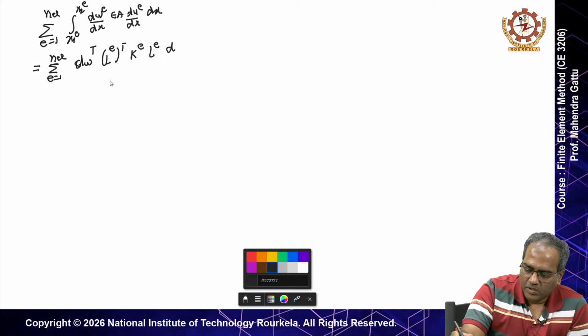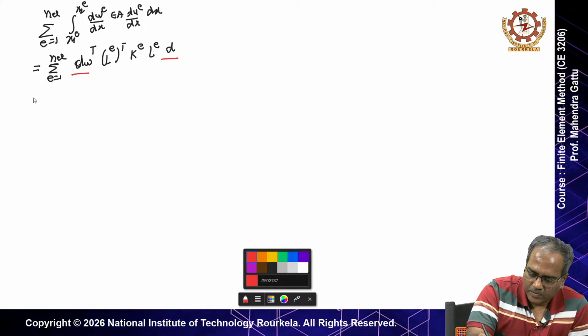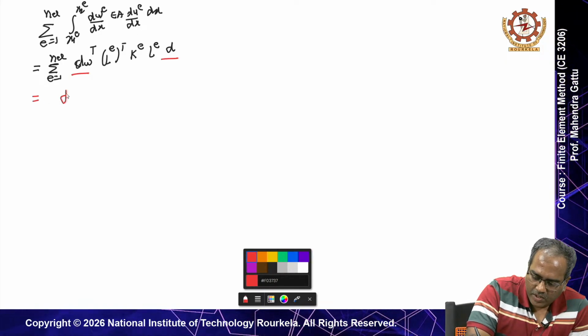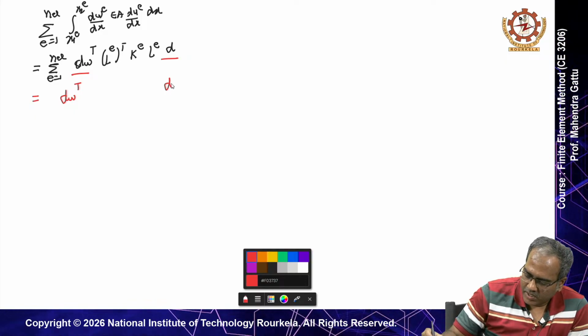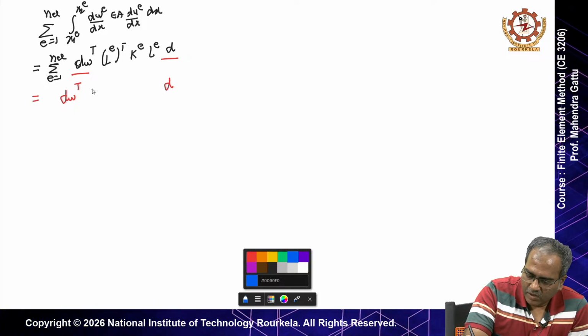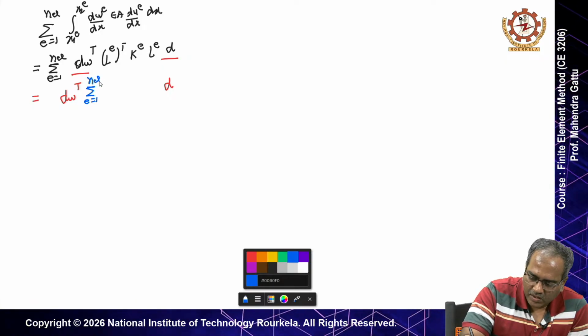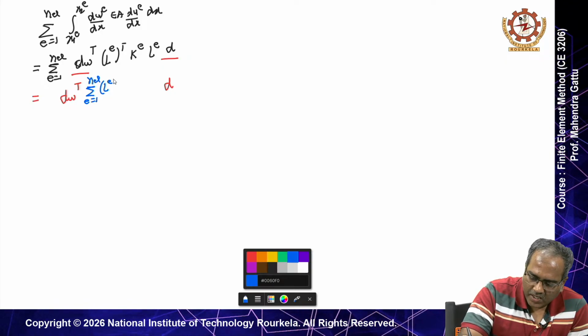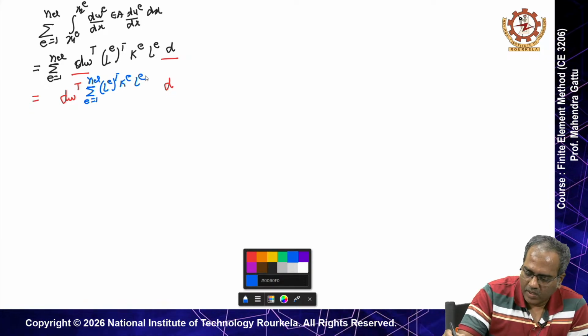Okay. So, we can take this term and this term out. So, I am taking them out here. I will get dW transpose and D on the other side, and the summation now will be from E equal to 1 to the number of elements of L E transpose K E L E. Okay.